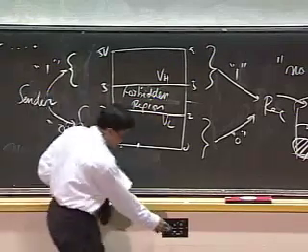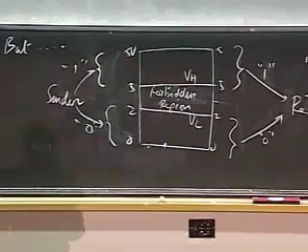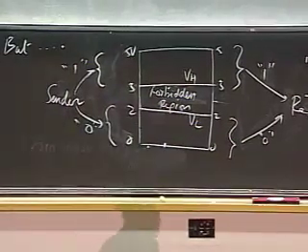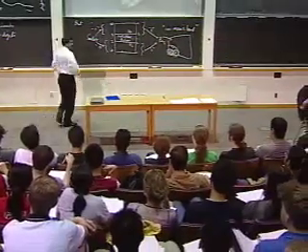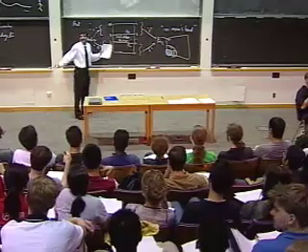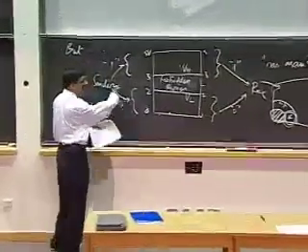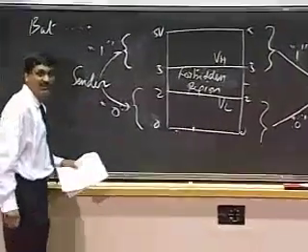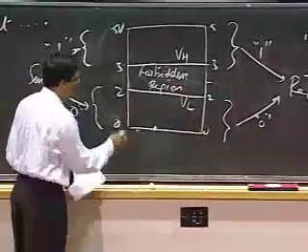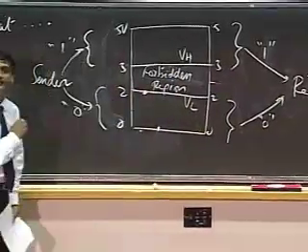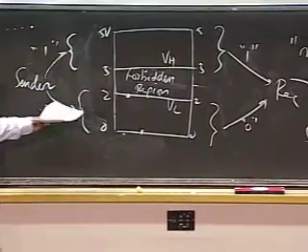So do you see what the problem is? Yes? If the sender sends a 1.99 and noise pumps it into the forbidden region. Exactly. So what if the sender says, look, it's legitimate. I'm Intel, right? They've told me, stick to 0 and 2. And Intel parts will be sending values between 0 and 2, and Motorola parts, which are receivers, have to receive 0 and 2. So Intel can send a value of 2 volts. I mean, they can, because it's 1.99 or 2. It's legal.